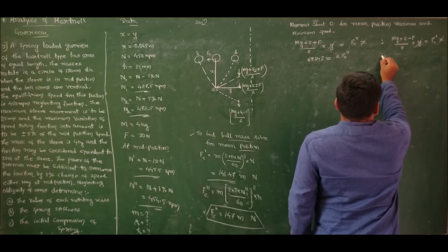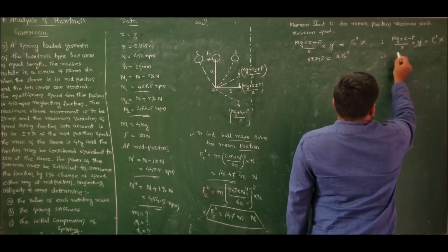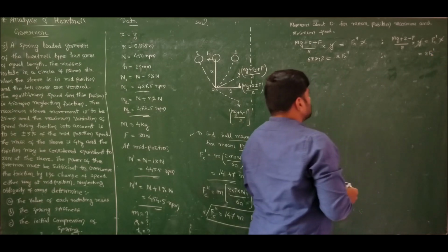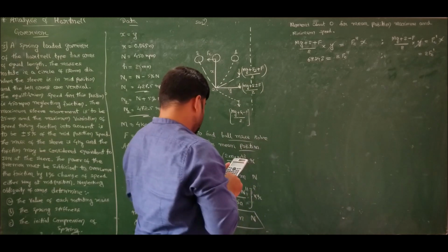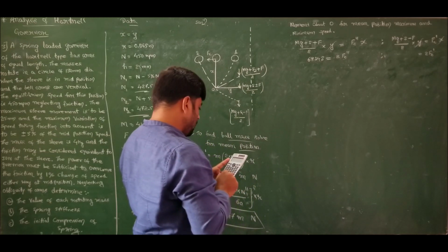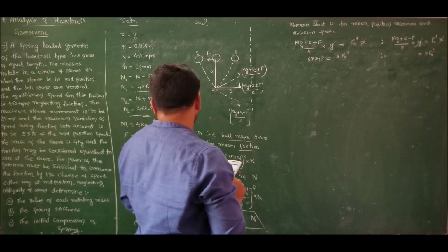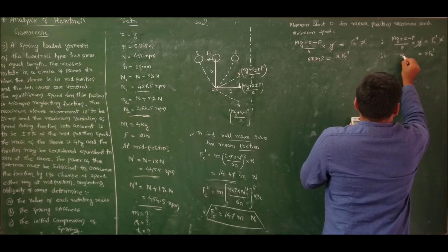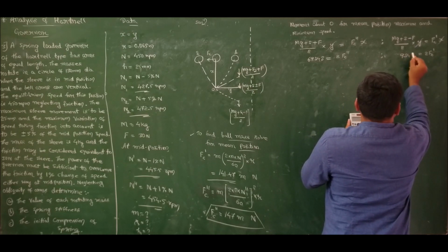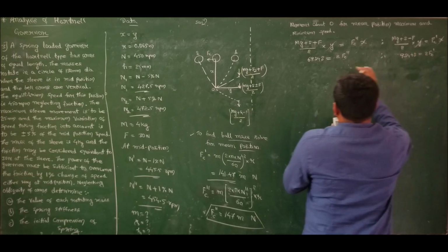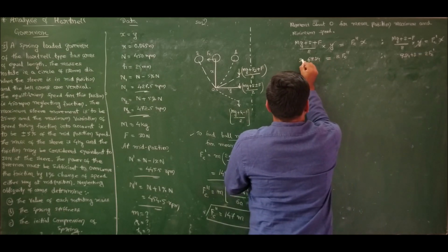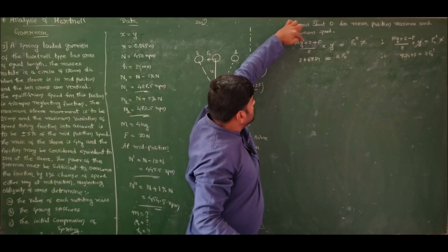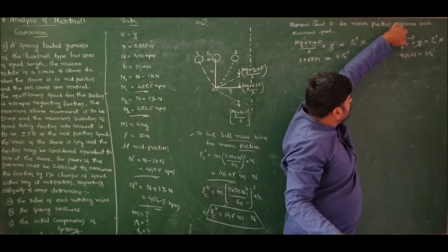Similarly here, if I solve, what am I going to get? This is equal to 2 times Fc dash, that is mg minus f, that is 4 kg is capital M into 9.81 minus friction force of 30 Newton, which is 9.24 plus S. This is S plus 69.24, correct? Mg plus F is known, S is unknown. Mg minus F is known, S is unknown.